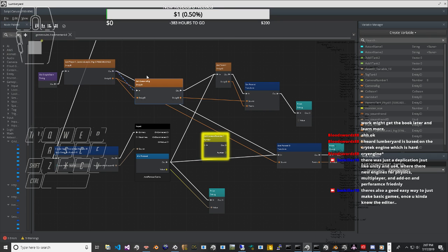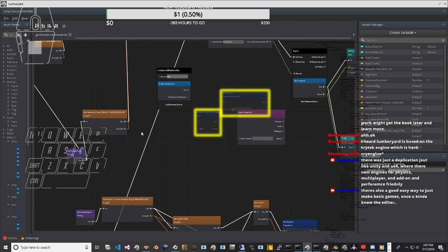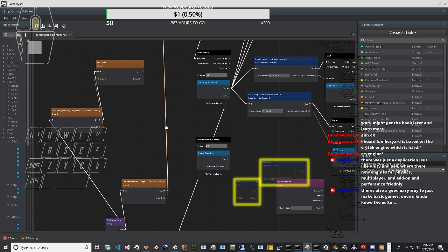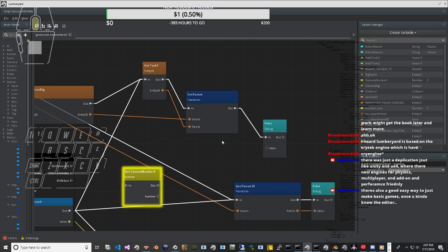Since the pneumatic tire compresses radially under the weight of the car, its radius is actually smaller than the unloaded radius at the point of contact, where it sticks and acquires linear velocity equal in magnitude and opposite in direction to the hub velocity. Since smaller wheels spin faster than larger ones at the same speed, the pneumatic tire spins faster than the equivalent rigid tire of the same unloaded radius.